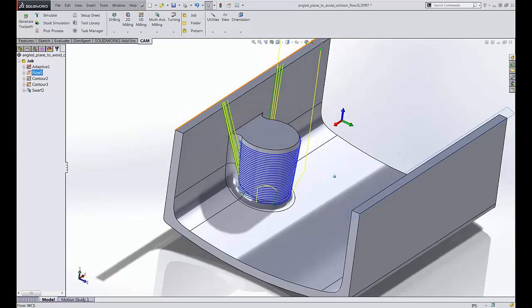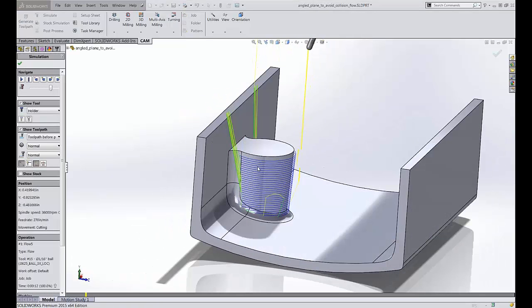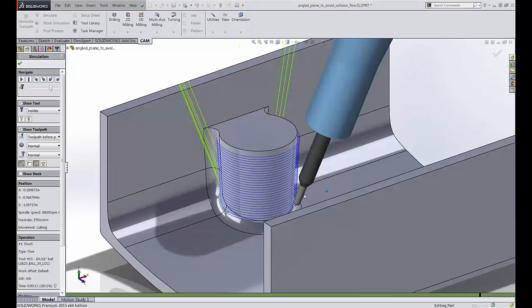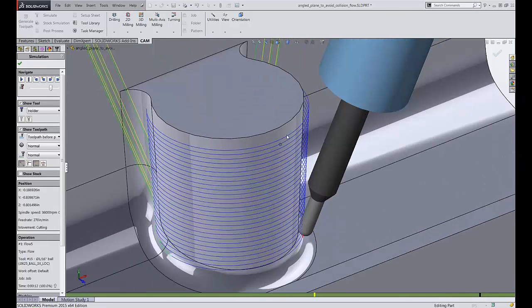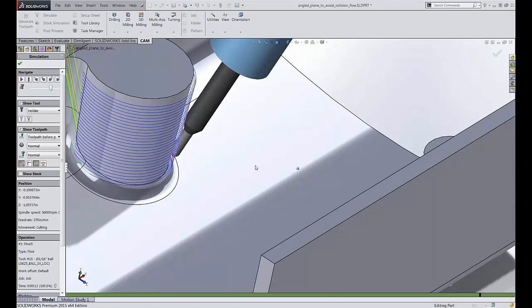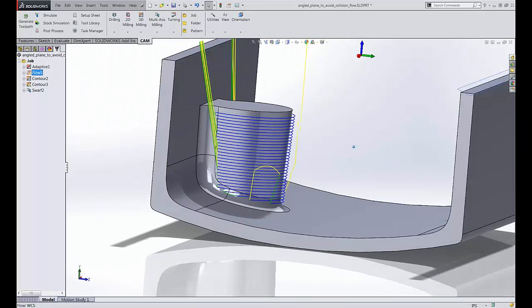Basically what we need is for this toolpath to not run into this wall, right? Otherwise it's great. It's not shanking out. I've got enough tilt already. It's contacting all the way down because it's flow and it generated those toolpaths based on the UV of the surface, and it's good otherwise. It just wants to tilt in the direction we don't want it to.